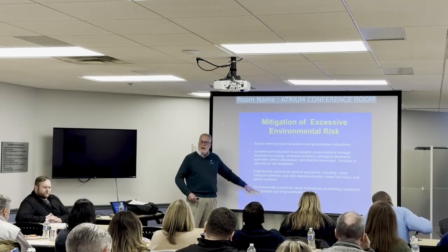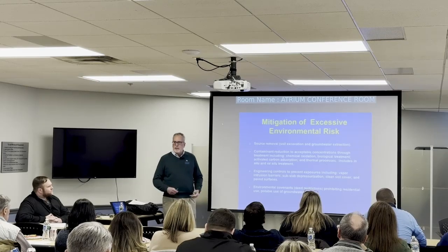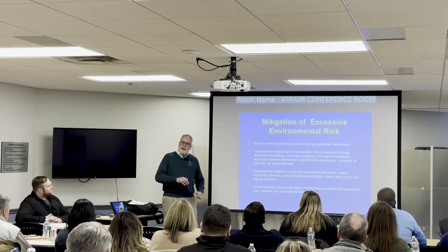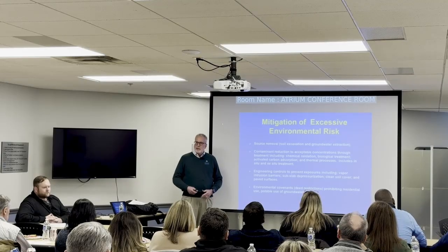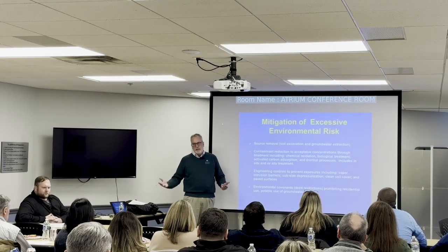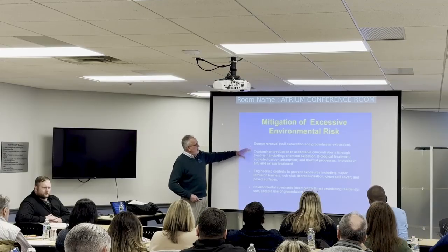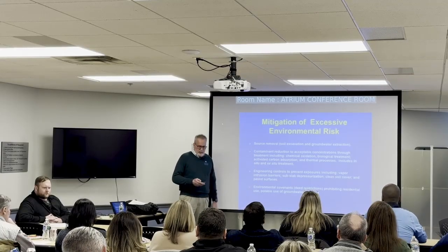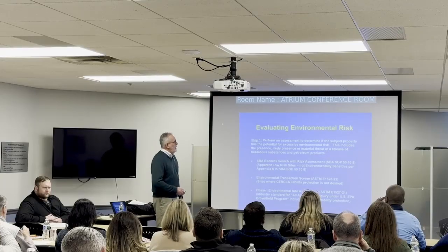Clean soil cover at sites. We've worked on sites where we put down basically a safety-type material that's orange, buried under 2 feet of clean fill, and supposedly if anybody in a commercial setting goes down and sees that, they know, hey, you're not supposed to go any further. There's a direct contact risk. So eliminate it, reduce it, or control it. Those are the big picture on what you do to mitigate excessive risk.